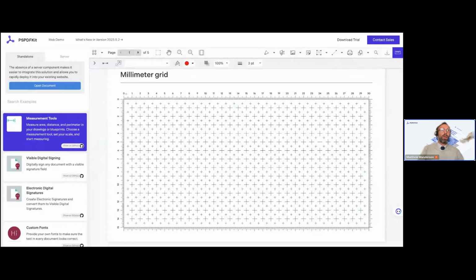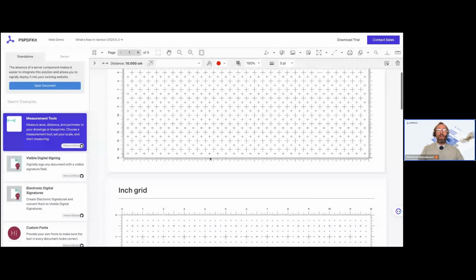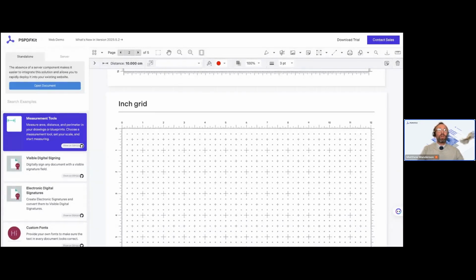And now when I take my new measurement and I go to 10, there. So what I did there, previously I didn't snap the first part, so when I clicked on it, it didn't snap in. But now I've snapped it to 0 and I've snapped it to 10. You can see we have an exact precision there for the distance. So now we know it's calibrated. Potentially we can start taking different measurements from here.